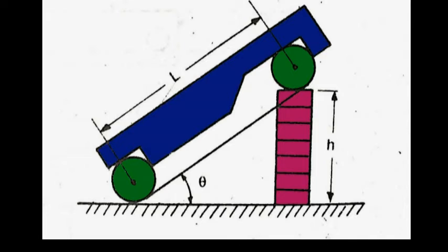So the main features of this sine bar: the upper and lower surfaces are flat and parallel with respect to the datum surface, and the side faces have flatness, squareness to the upper surface and squareness to the axis of rollers. The end faces have flatness, squareness to the upper surface, and parallelism to the axis of rollers. These are also built with fixed rollers, which have straightness, cylindrical accuracy and mean diameter.